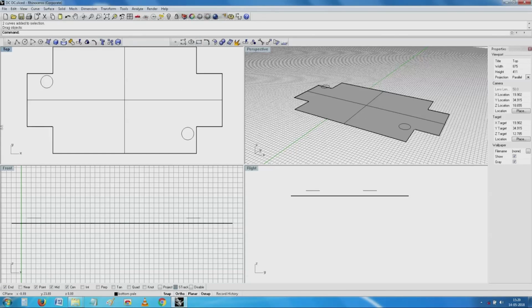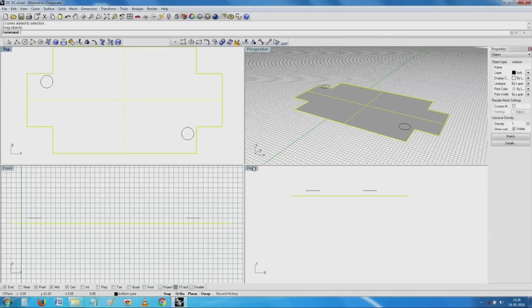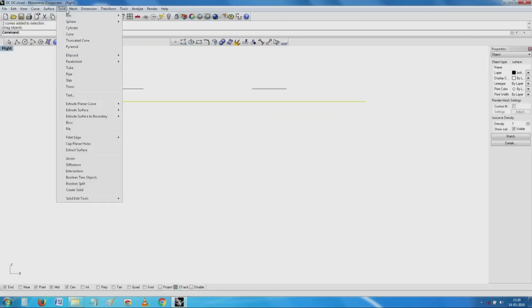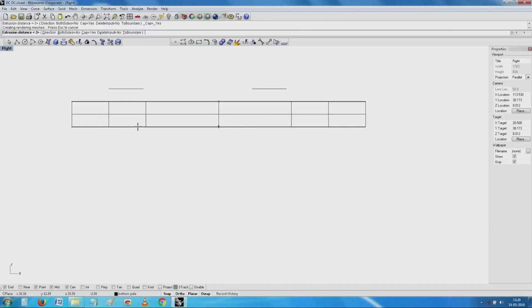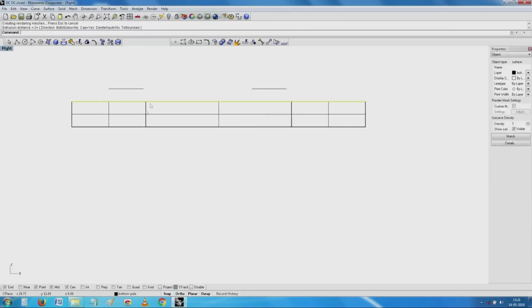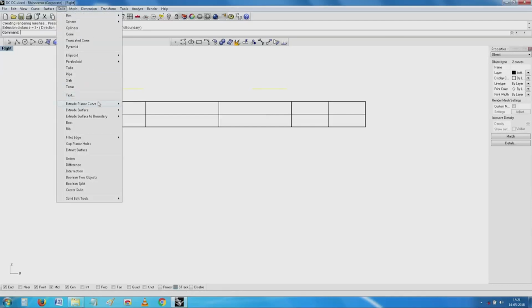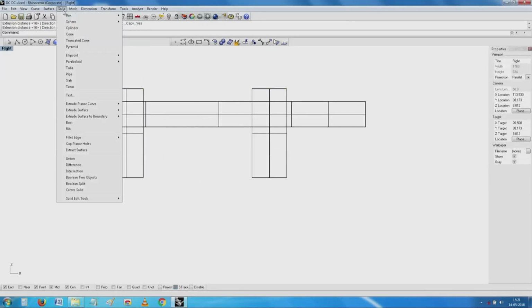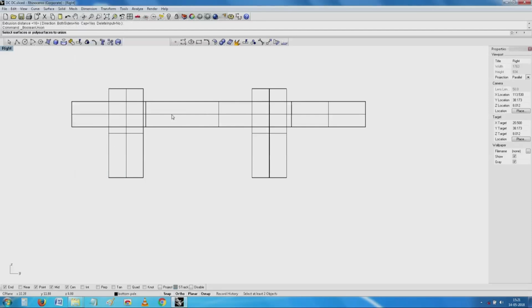However, anyway, since eventually I need to convert it into a thick plate, I will make it into a 2 mm aluminum plate. Now, I will extrude the solid. I have a 2 mm aluminum plate, then I make a solid out of these curves and make openings by making a difference.